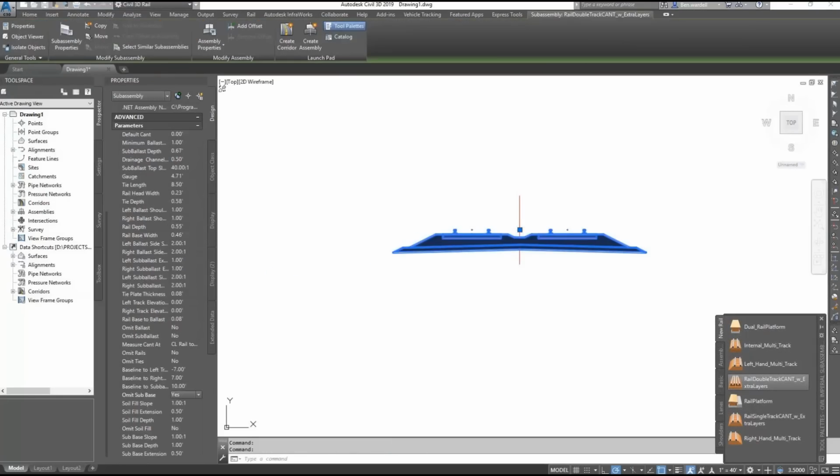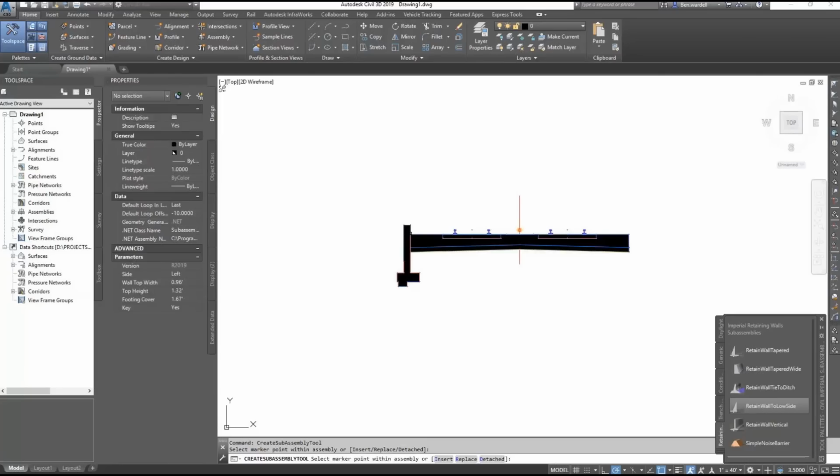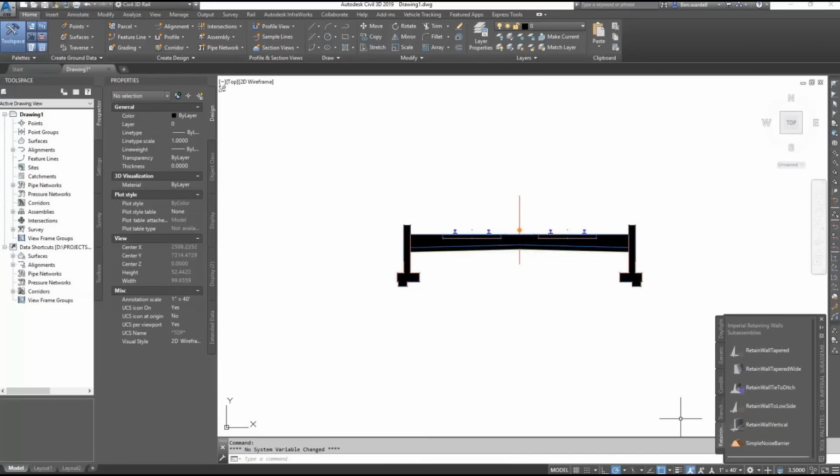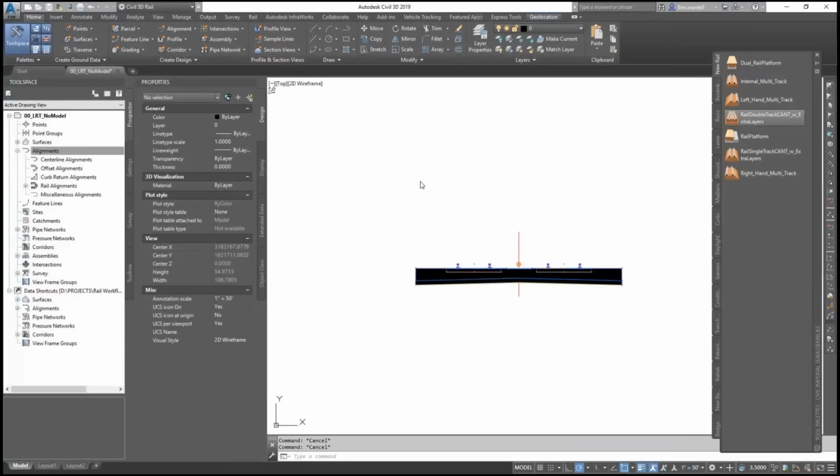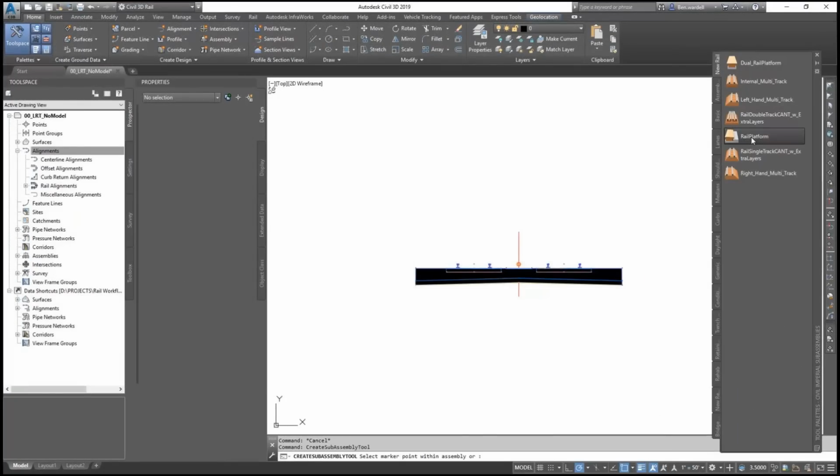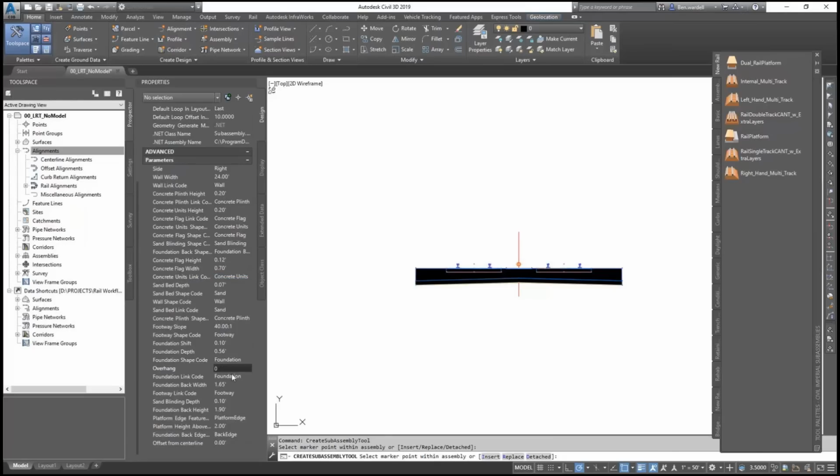And then in this case, we've got some constrained right-of-way. We're actually going to set this up, and we can set the side limits of our assembly essentially vertical. I set them at 0.01 to 1, and so they're essentially going down. And then we can add retaining walls on either side. The beautiful thing about these retaining walls is they work for cut or fill conditions. And so that's going to be useful anywhere we've got constrained right-of-ways, or where we know we're going to have some of those walls as well.